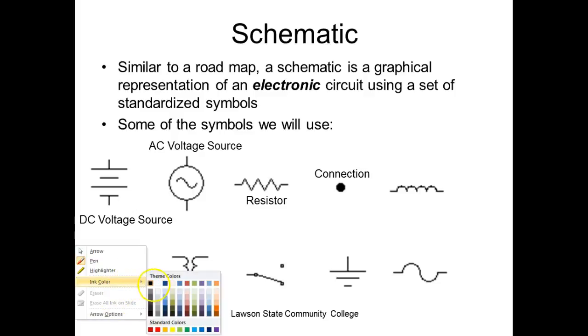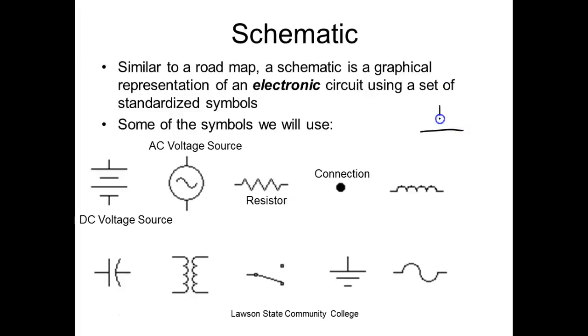Of course, a lot of people use it, where they have a crossing line and they come over here and do that. That's not a legal symbol. So what we know if we do this and don't put a dot, it means they are what? Not connected. If I put that, they are. So if you leave the dot off, it's going to be considered what? Not connected. And you'll lose points for it.